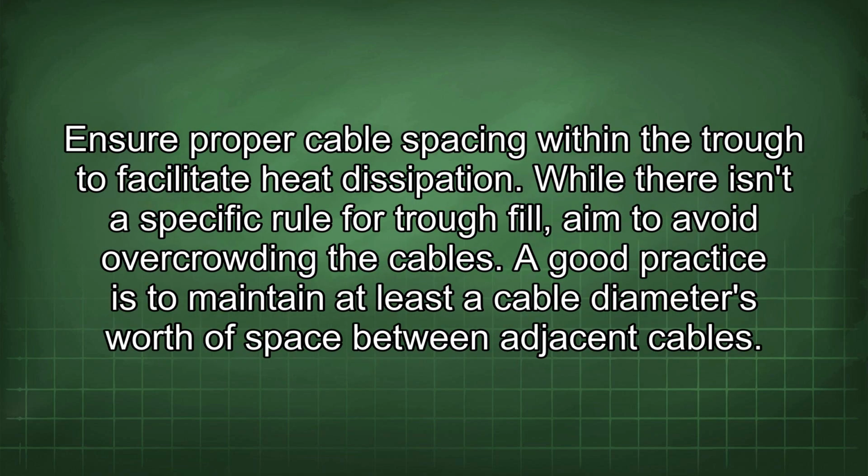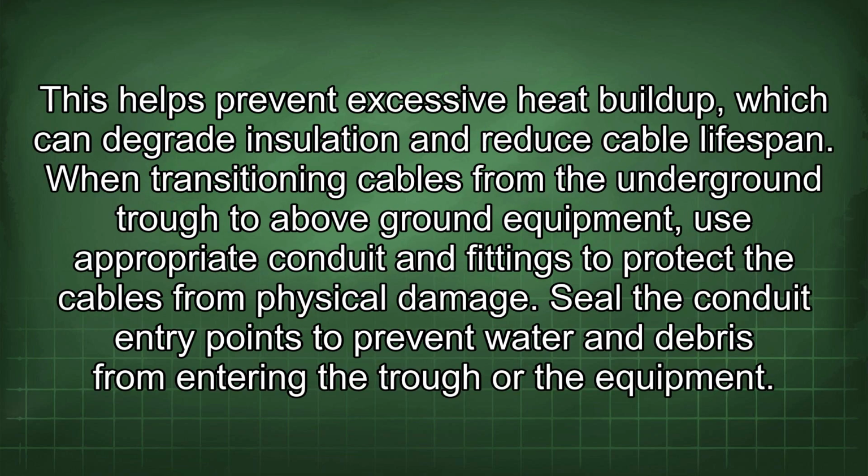Ensure proper cable spacing within the trough to facilitate heat dissipation. While there isn't a specific rule for trough fill, aim to avoid overcrowding the cables. A good practice is to maintain at least a cable diameter's worth of space between adjacent cables. This helps prevent excessive heat buildup, which can degrade insulation and reduce cable lifespan.